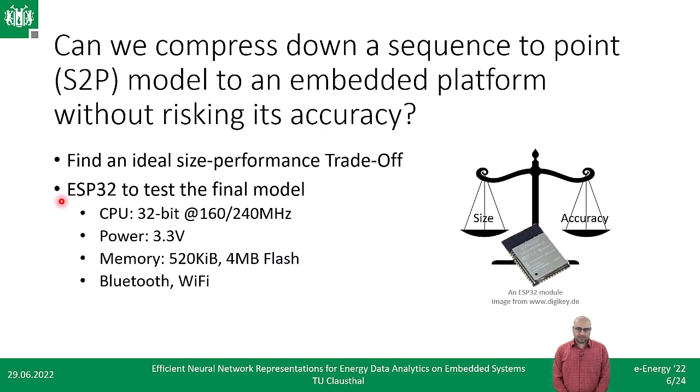produced by Espressif Systems. It has many communication options such as Bluetooth Low Energy, Wi-Fi, a 32-bit dual-core processor, and 4 megabytes of integrated SPI flash memory. And the ESP32 is not optimized for electricity meter applications. For instance, the built-in analog digital converter doesn't have a high enough resolution, but it's more capable than most microcontrollers in the next generation of smart meters. And there is already an energy meter that makes use of it, such as the expandable 6-channel energy meter from Circuit